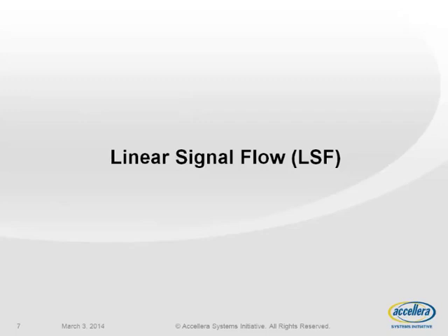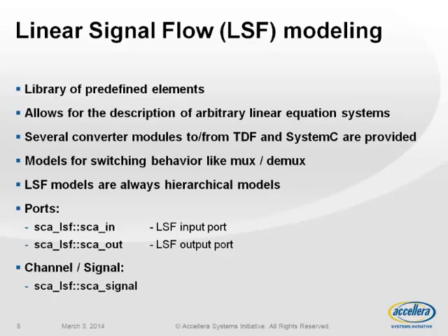After TDF, there is a second model of computation called linear signal flow. I will be very short on this. The idea is that the linear signal flow library uses predefined elements that can be used to describe any system of linear equations. What is interesting is that these LSF primitives can be connected to TDF ports. So you can embed LSF behavior within a TDF module.